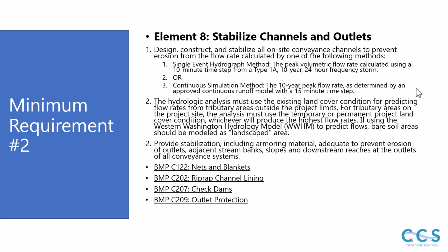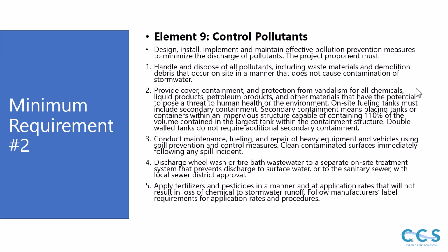Then element 8, stabilize channels and outlets. Design, construct, and stabilize all on-site conveyance channels to prevent erosion from the flow rate calculated by one of the following methods: a single event method or continuous simulation. The hydrologic analysis must use the existing, so it's just the same standards there. There's 4 BMPs for element 8.